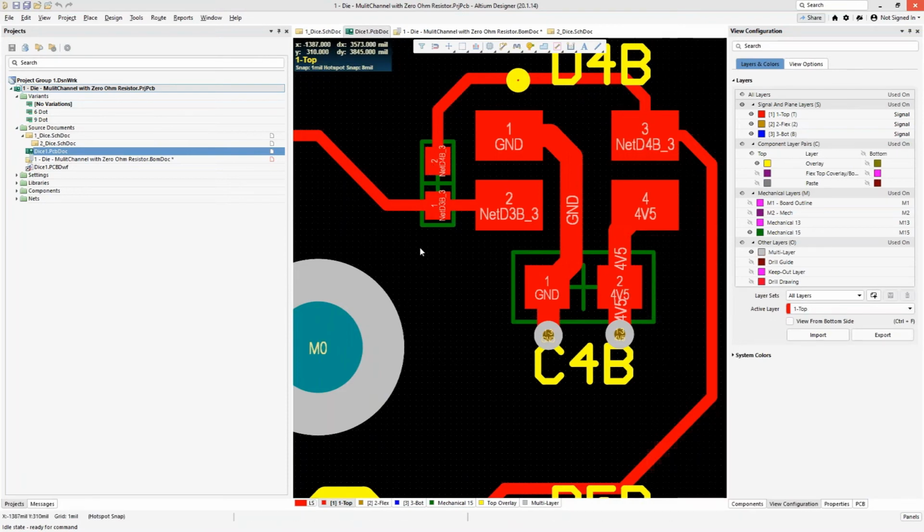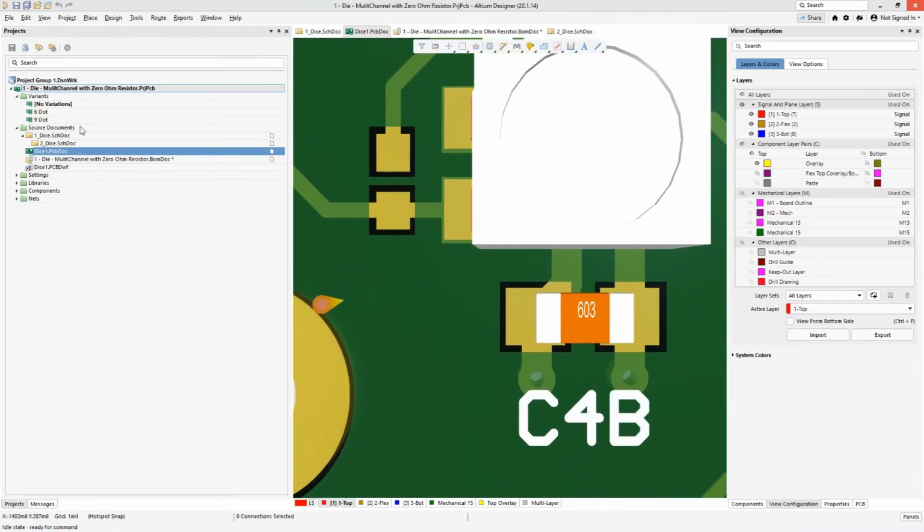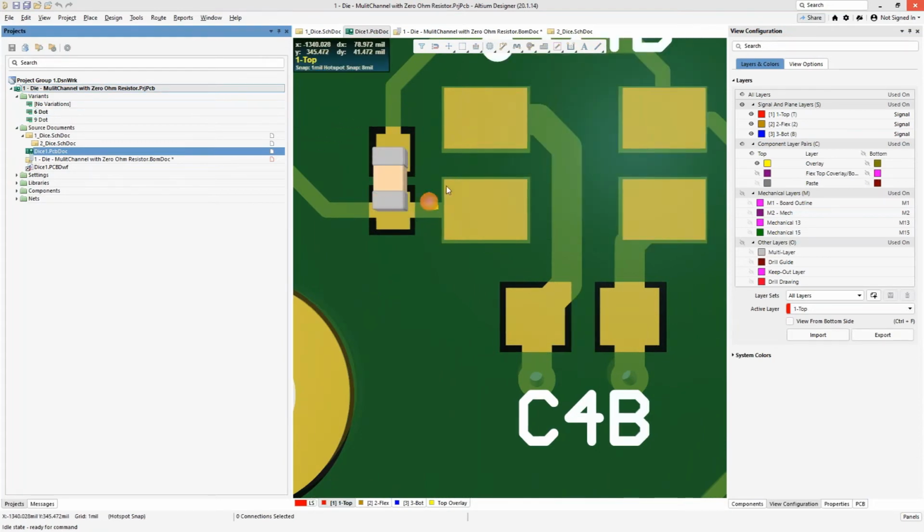Just simply, again, it goes back to the rule that even if I have an alternate part, it's really about which part do you want to populate, this part or its corresponding alternate part. And that's why if you look here, and you'll see this if I hit the 3 key, that if I go to my 6 dot here, double click it, remember this D4 and this little resistor are the alternate parts to each other.